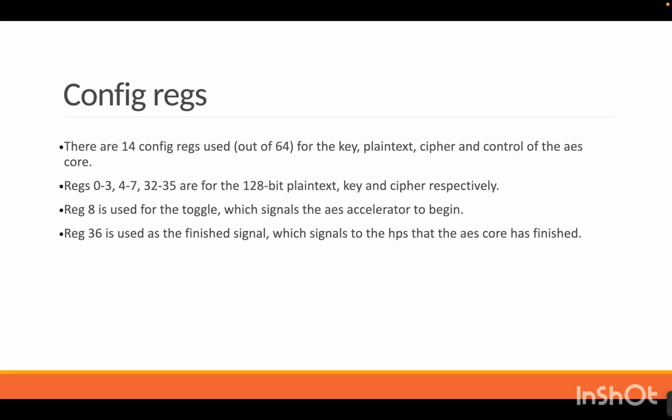Config registers. So out of 64 available registers, we used 14 for this project. Specifically, registers 0 to 3 store the 128-bit plain text, registers 4 to 7 hold the encryption key, and registers 30 to 35 capture the 128-bit ciphertext output from the AES core.